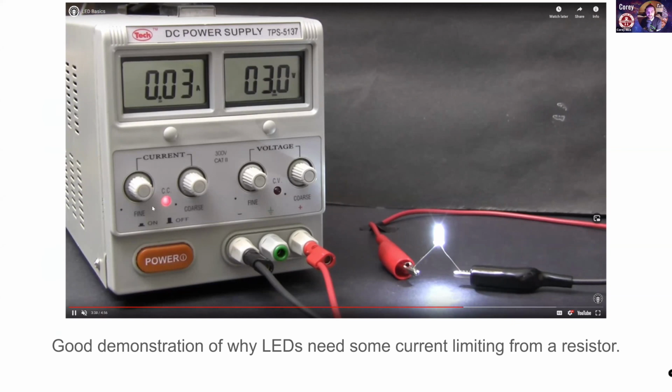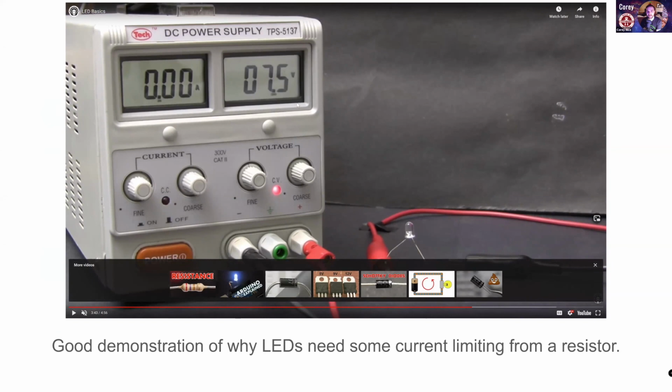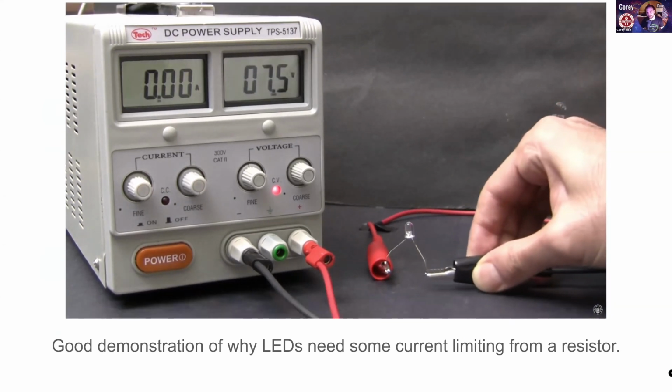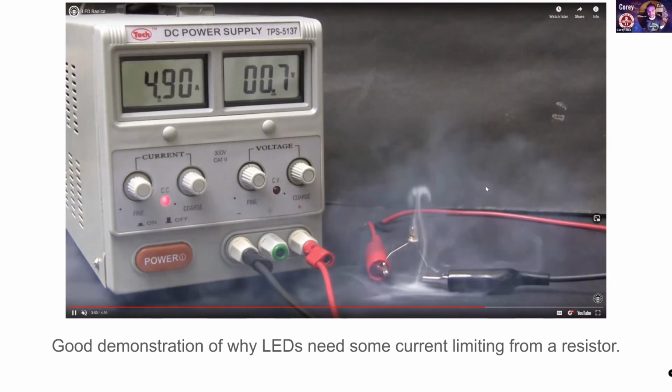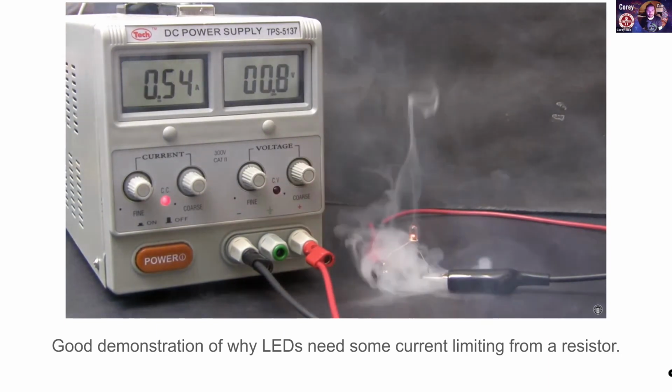But if he turns this off, different and interesting things will happen. So here he's got it disconnected and it's up to 7.5 volts and there's no light on the constant current side. So he's got a fixed voltage, but he's going to let the current do whatever the current does. So he's essentially taken his foot off the brake pedal. And so here you can see you really can blow these, right, with puffs of smoke and they get hot and then the whole thing is dead.